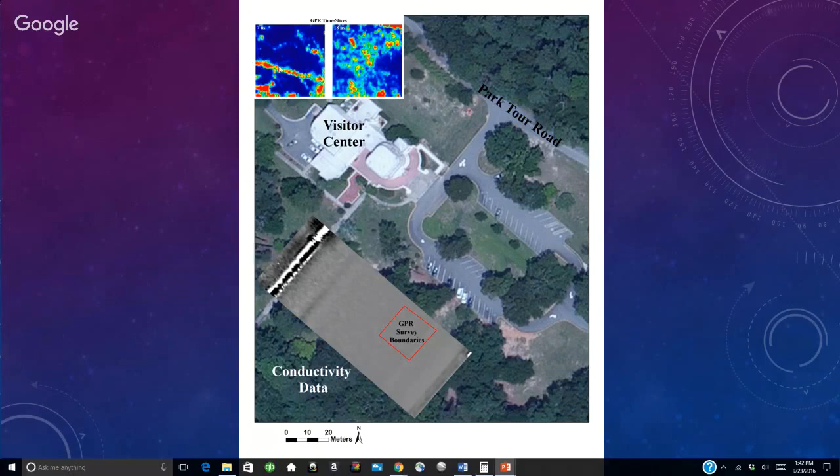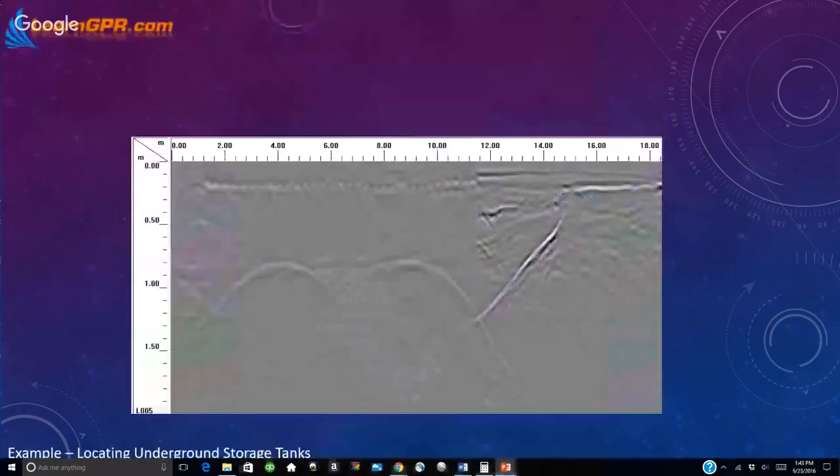And that's this linear reflector right here. By the time you get to 1 meter deep, it's gone. Can't really see it. This may help you get some indication of pipe diameter as well. But we were able to see this here, and it's probably a ceramic drainage system is what we interpreted it as. Obviously, it doesn't hold any sort of current, or else it would have been identified by the conductivity meter. And so it doesn't hold current. It's clearly linear. It's going down slope into a stream, and so it's probably a drainage system.